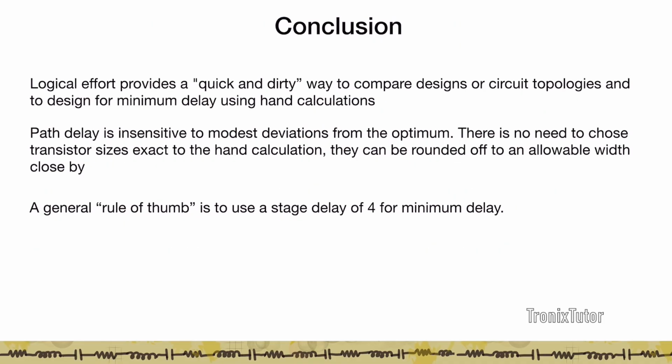So to conclude, logical effort provides a very quick and dirty way to compare designs or circuit topologies, and it helps us design a path for a minimum delay, most importantly using hand calculations. So it gives you a feel for how you should design the path for an optimal delay.